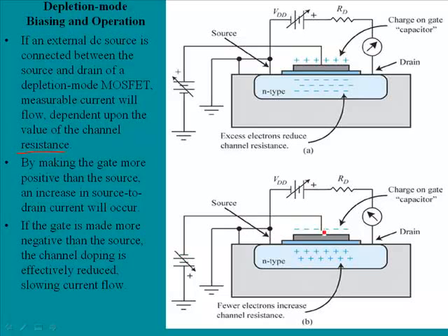And so now we're putting a negative voltage on the gate, and we're having that same capacitance effect, except that now the electrons are on the top plate, and we have a positive charge on the bottom, and this effectively reduces the doping level in the N-type material, and depending on the amount of negative voltage, this will become extremely resistive, and it will impede current flow.